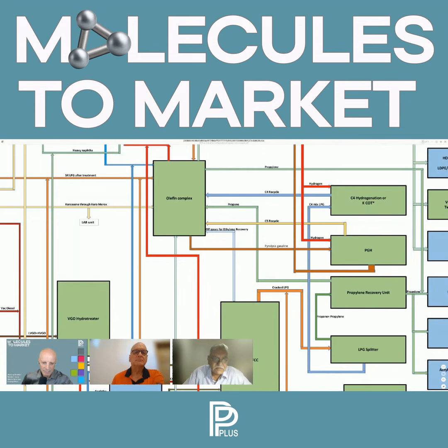Now, so I have a feasibility document, I have a clearance from the investment board to develop a DFR. First prerequisite of DFR is I must have the technologies in position. Because in the feasibility report, I shared an intent. In the detailed feasibility report, it cannot be an intent. It has to be a firm information. So the most important part is I must cut down that variable of options of licensors, and I must freeze on the technology.